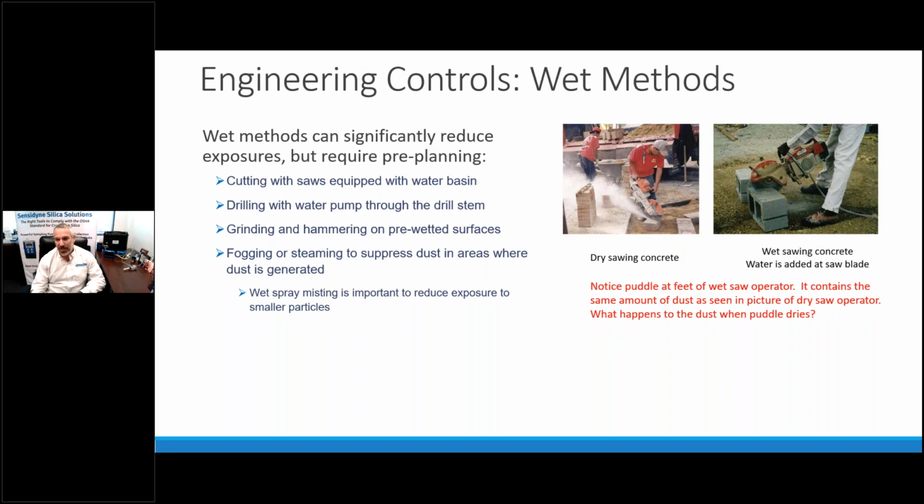One of the things that you need to be aware of, though, is you're going to concentrate this dust into this reservoir of water. If that water ends up drying up through evaporation, you're left with these very fine particles of dust that can now be aerosolized. So it's important that you get that level of dust in that water back up, or prior to it becoming aerosolized, use a dry HEPA vac to collect that material prior to it becoming aerosolized.